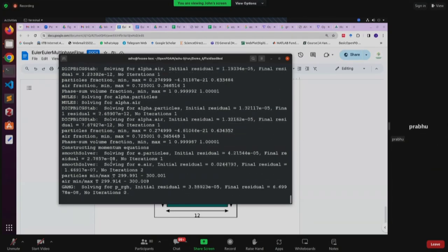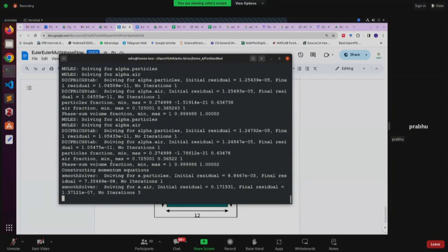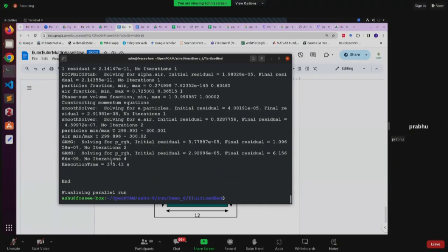So sir, that is possible. Previously we had done a nozzle case. Is that a similar condition? Correct. What you did for the nozzle is exactly the same thing. If you make the axis along the z-axis instead of along the x-axis, then you can consider it like a pipe, give an inlet, and the two patches will be cyclic. Okay, sir. Exactly, that is what you can do.